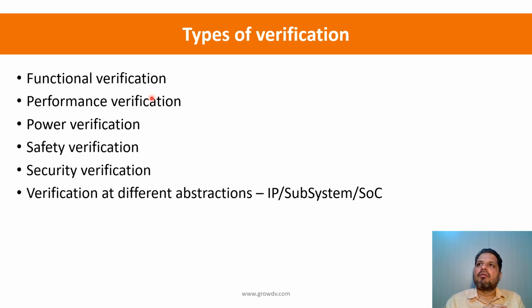And then typically these days, if there are a lot of power constraints, if the design is going into mobile devices or very power constrained types of designs, a lot of low power techniques are used. They use multiple power islands, and different voltage levels are being utilized, and the power domains could power up and power down.